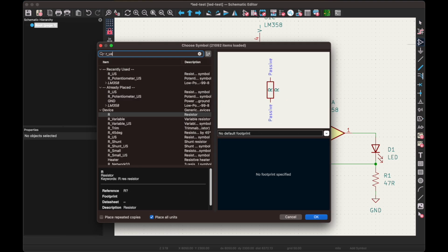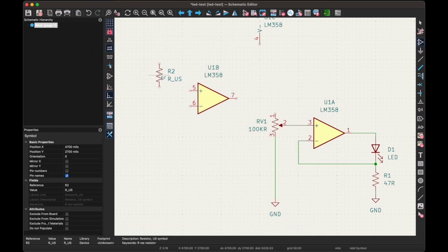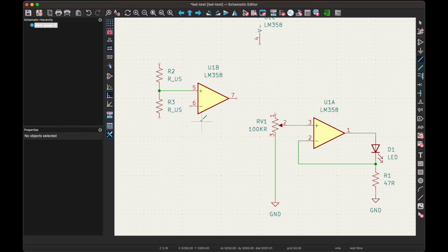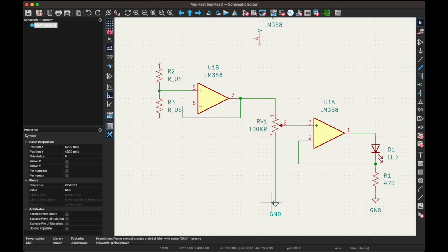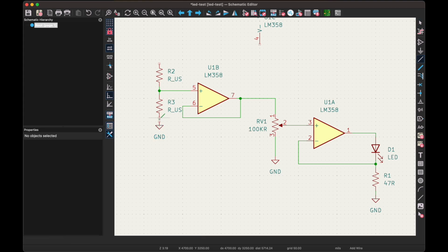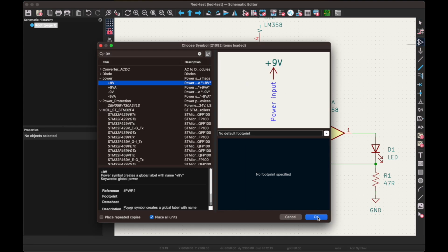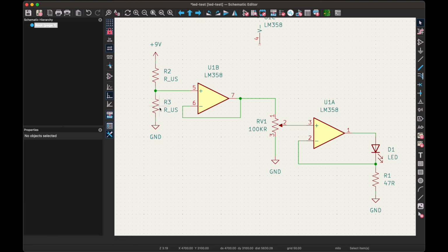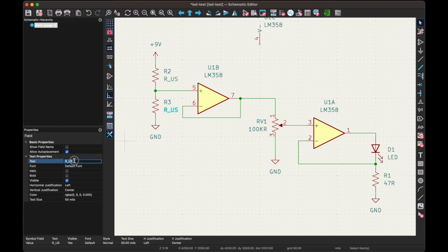We'll create a 1 volt reference using a voltage divider. Now all we have to do is buffer the output and connect it to the second side of the pot. We'll connect our resistor divider to ground and a 9 volt supply. It's easy to divide this voltage. We need to drop 1 volt across the bottom resistor and 8 volts across the top. We'll get close enough by choosing a resistance of 1K for the bottom resistor and 7.5K for the top.